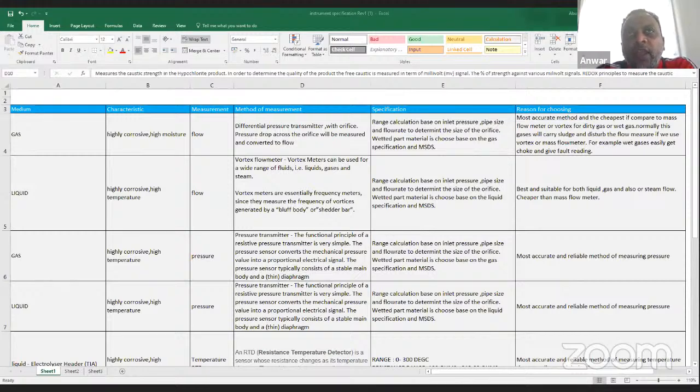There is no delivery system that can do that except a manual loading system. So when you have a salt environment, it is very, very corrosive. You have to choose not only the wetted area of the pump, but also the external material of the pump, which can last in that environment.